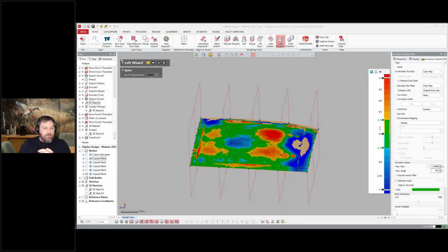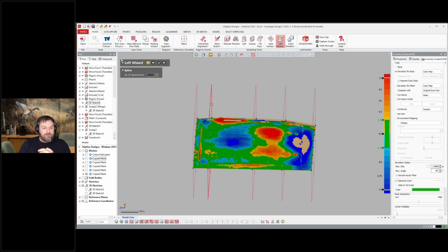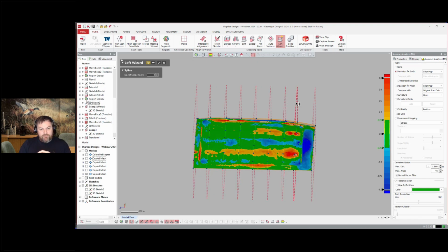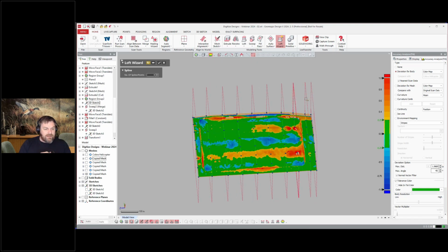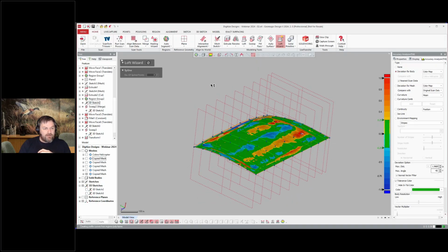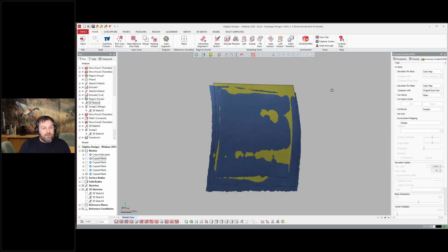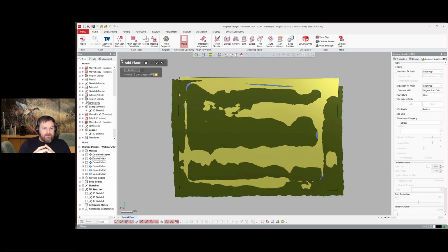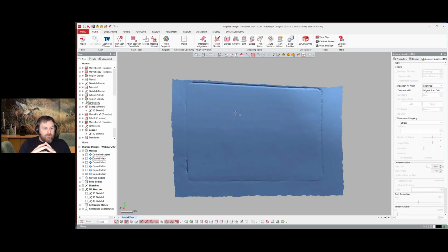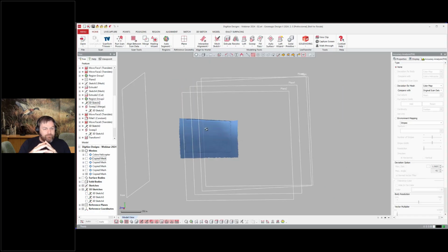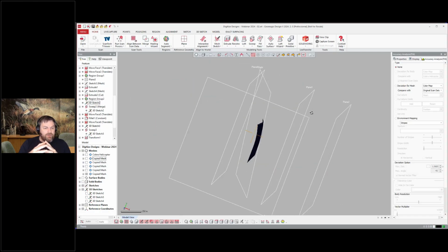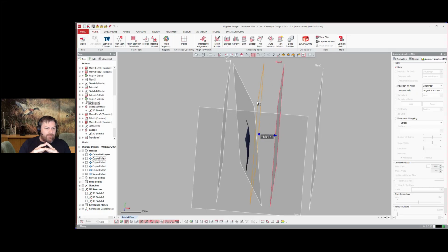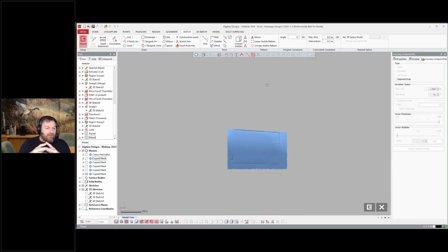And then I can move the cross sections on this loft wizard that it's creating automatically for me, right? And then I can drag out the different cross sections and then have it create a nice clean surface loft through that information. Now, once I do that, the next steps here, if I was going to create a simple panel like this, is create that panel and then extrude and create a plane here. And you see I can draw the outline.